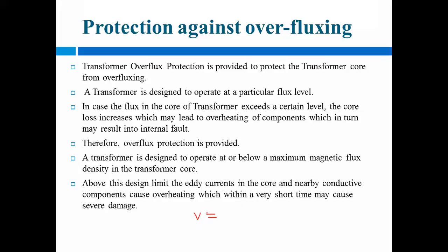So V is equal to 4.44 f phi m N. N we can consider as the number of turns. This is the relation between the flux and applied voltage.